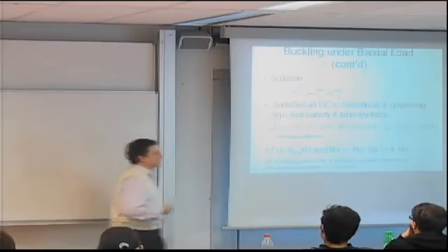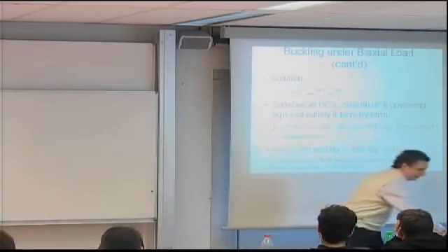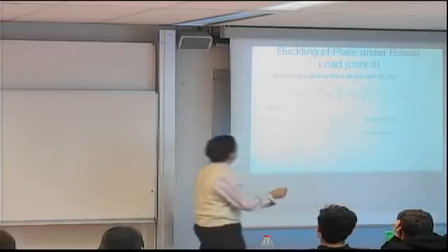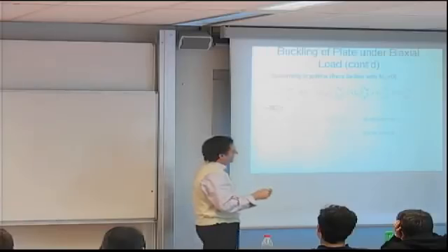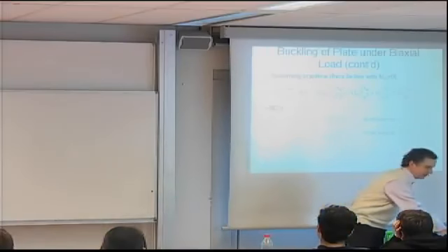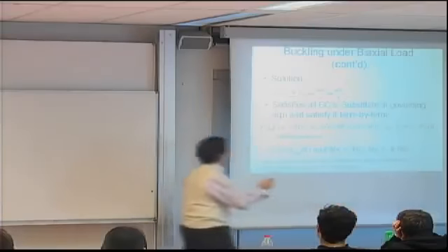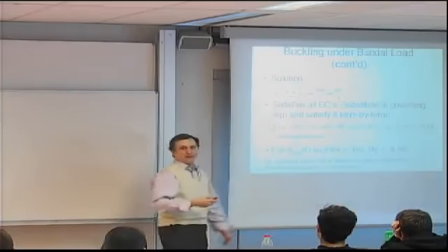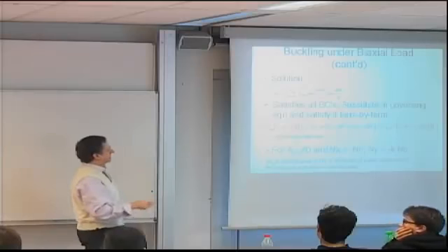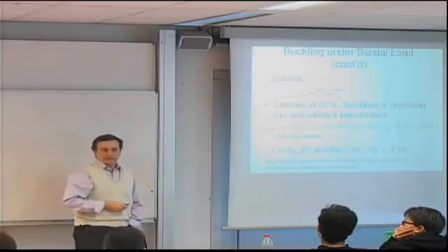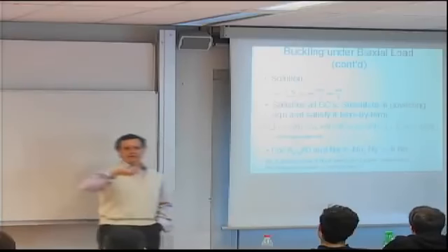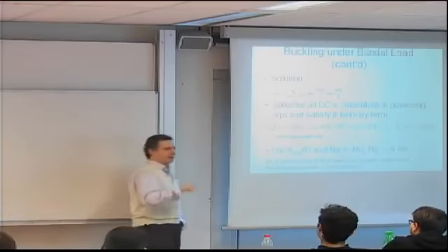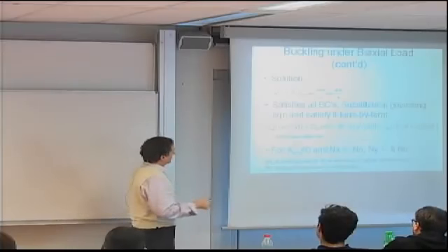So if we then substitute at the governing equation, this one here, there will be only even derivatives of W, and therefore the sines that start with W will reproduce themselves with some coefficients, but this sine times sine will reappear, and therefore all I have to do is equate coefficients of the sine times sine of equal indices m and n. I pick a value of m and n, find the corresponding coefficients. On the left-hand side I would have this, on the right-hand side I would have this.